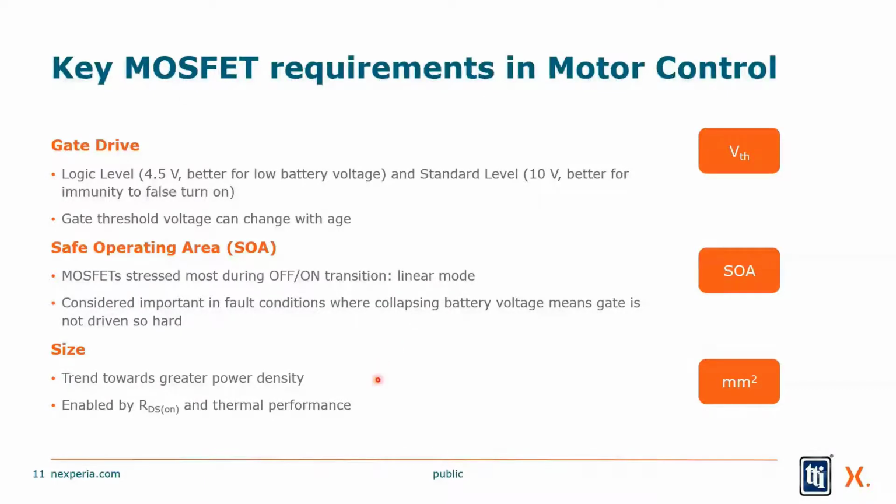And then finally, size. I want to put these MOSFETs as small as I can. The common standard today is a 5x6 millimeter package. Hold up your hand and look at your fingernail. Your pinky's probably on the order of 5x6 millimeters. We're talking very tiny parts. There's also 3x3s available, 8x8s, and heck, there's even 2x2s and 1x1 millimeter packages.